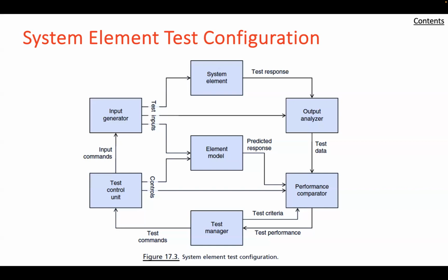Three, the equipment used to test separately an individual component may not be exactly the same as that incorporated into the integration test facility, or its calibration may be different. And four, the prediction of expected performance of the element under test by the element model may be imperfect due to the impossibility of modeling exactly the behavior of the test equipment.